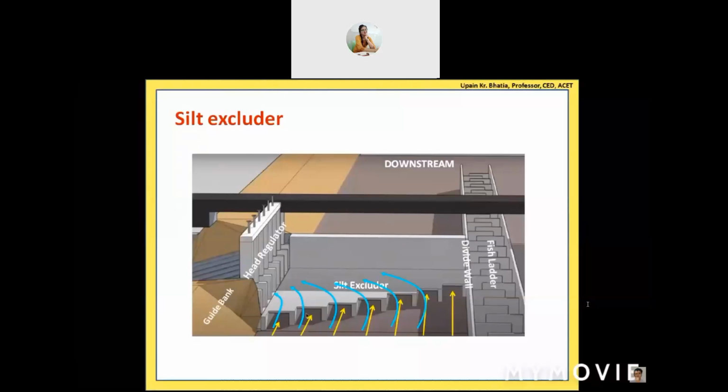The water is not crystal clear. It can be turbid also. Okay? That means sediment can enter into the canal also. The 100% elimination of the silt is not possible through any of the structures. But by utilizing this concept that the silt concentration is more in the bottom layers, we can achieve cleaner and cleaner water in the canals. Okay. So this is the device category 1.